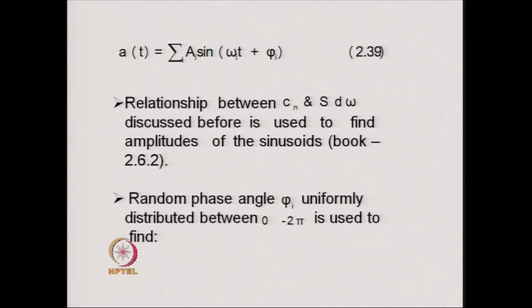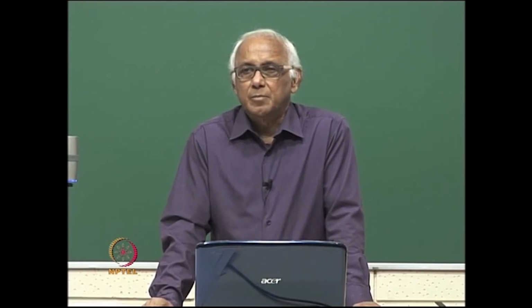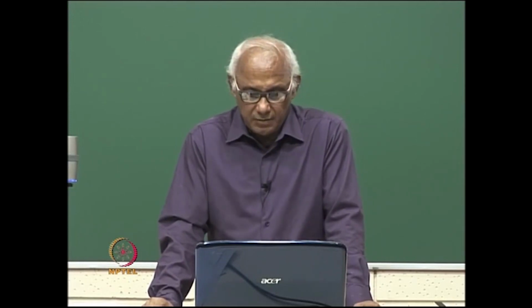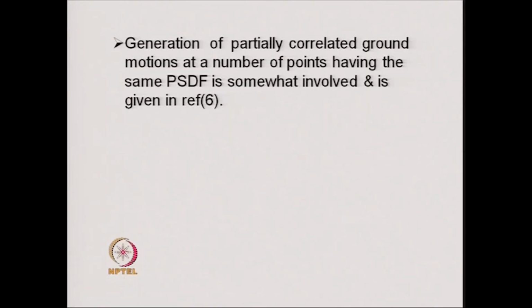Many standard programs are these days available in order to obtain the time history of ground motion which are compatible with the power spectral density function or a given response spectrum. Generation of the partially correlated ground motion at a number of points having the same PSDF is somewhat involved, however, the methodology is given in reference 6 of the book.